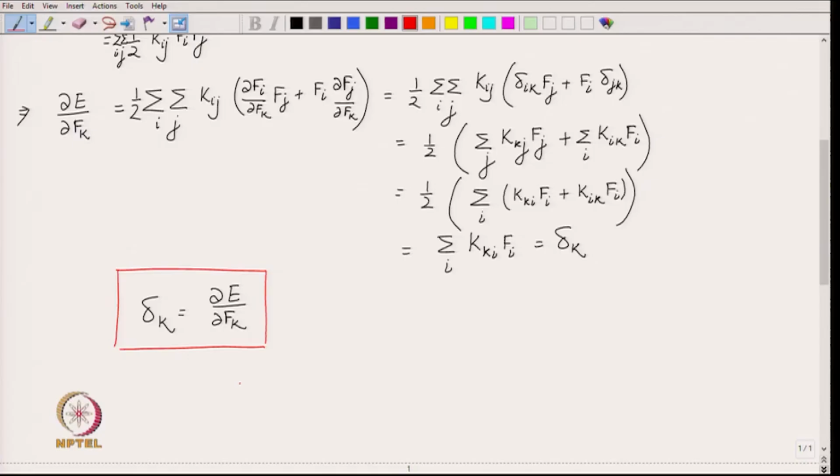So, that is Castigliano's first theorem, and you will see that this is going to be very useful while finding out displacement or rotation, which is like a generalized displacement. Without solving the Euler-Bernoulli or Timoshenko beam theory, we could simply write the energy of the beam in terms of the applied load and take the derivative to get the corresponding displacement. So, writing down the expression of energy is really critical here, then only can we use these theorems.